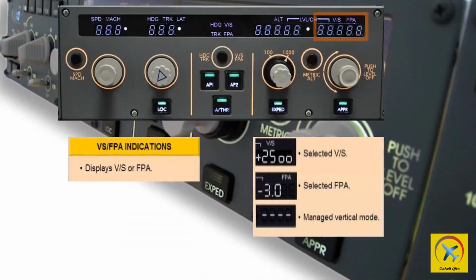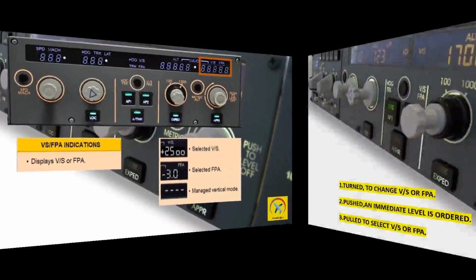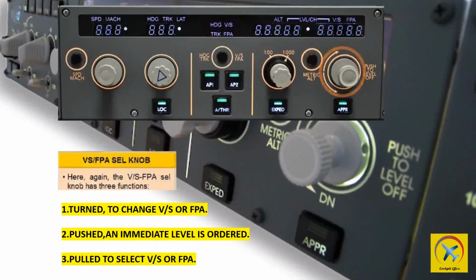The vertical speed or flight path angle window displays the selected vertical speed or flight path angle. It normally displays dashes when not in vertical speed or flight path angle mode. The vertical speed or flight path angle selector, when rotated, changes the vertical speed or flight path angle displayed in the vertical speed or flight path angle window. The vertical speed range is from plus or minus 6,000 feet per minute. The flight path angle range is from plus or minus 9.9 degrees.